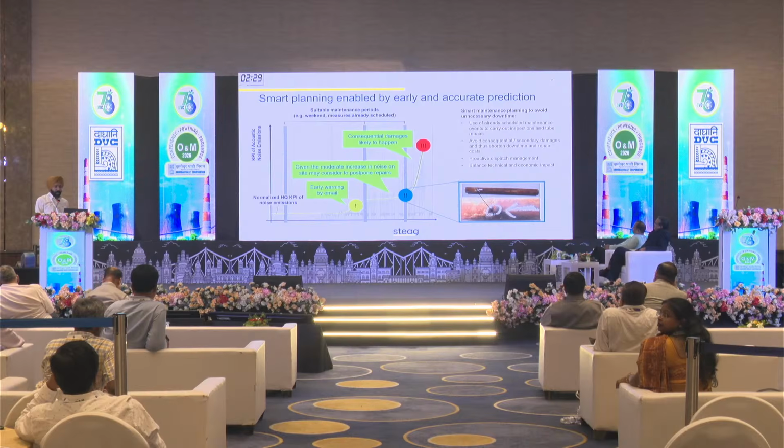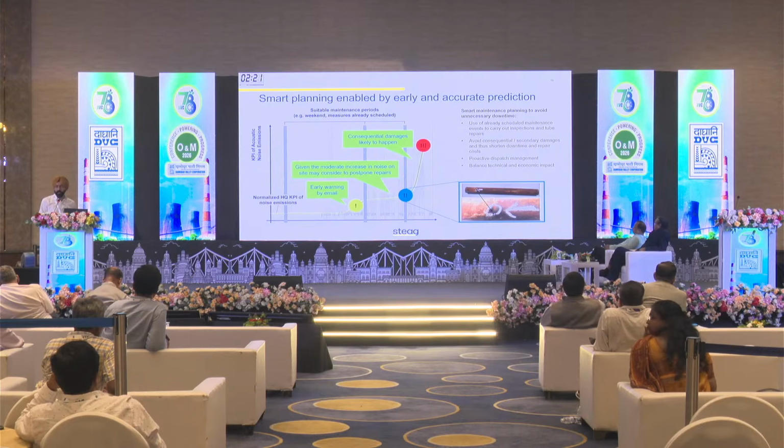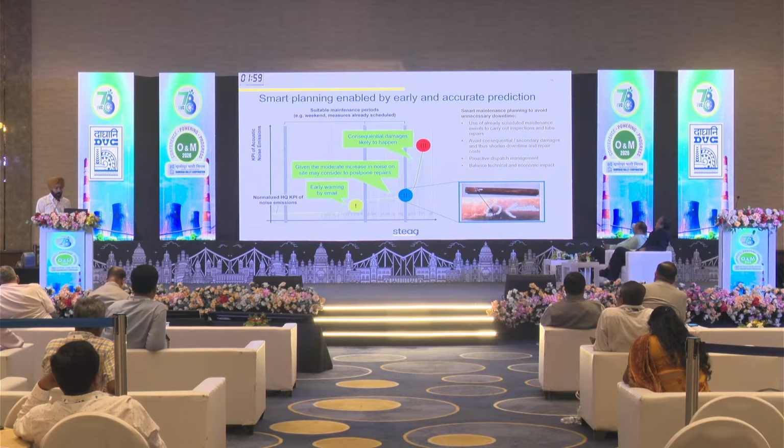So basically it's smart planning enabled by early and accurate prediction based on AI/ML. Whenever you have an early alarm for leakages which have started in the boiler, and if there is already a planned maintenance activity in the future, then it can be used for the inspections and then correction also, and the unplanned outages can be reduced.